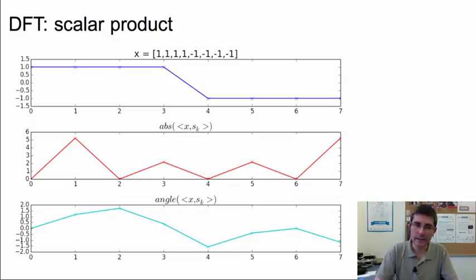We'll get the magnitude and the phase, so it's going to be a complex spectrum, and we can display it as polar coordinates. And here we can see that in this signal there are some frequencies present. The frequency k equals 0 is not present.